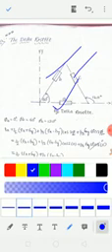Now if you look at that, here I can say A, and B, and this one is C. So this one I can also write as epsilon A, epsilon C, and this one is epsilon B. Now you want to determine epsilon A, epsilon B, epsilon C. You already know that the angle phi A equals 0 degrees, phi B equals 60 degrees, phi C equals 120 degrees. Similarly I will take the general equation and substitute 0 degrees, and we will get epsilon A equal to epsilon x.